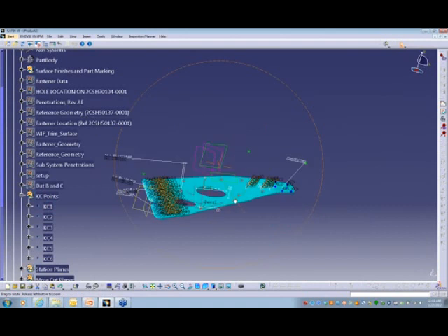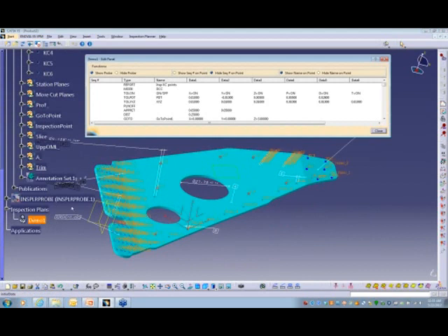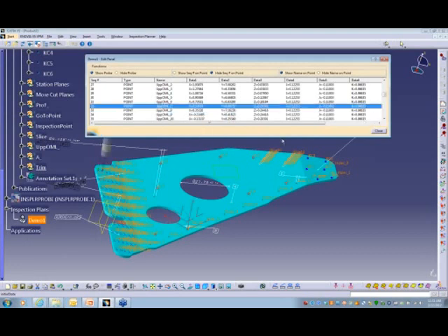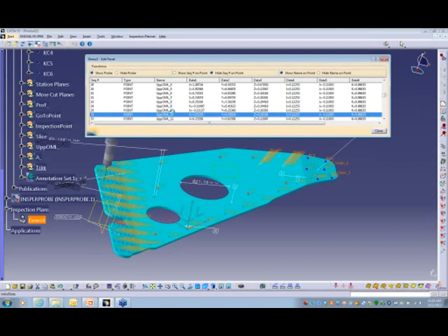So we run our simulation. We see everything is okay. We're happy with that. If we wanted to, we could go in and edit this information by right-clicking. There's editing capabilities. And another time that you can simulate too is anytime you pick something in the edit window. You could walk through with your keyboard and simulate this way too and see exactly what you're doing. So I can walk through a simulation this way too. Go into the different holes. So you're happy with your program.